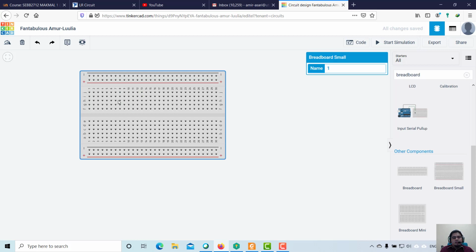The purpose is that, in practice, by having this kind of architecture, you can minimize using too many jumpers to design a circuit. Let's say you have a very complicated circuit. If you know that this photoboard has its own built-in jumper or built-in wire inside it, then you can utilize it.